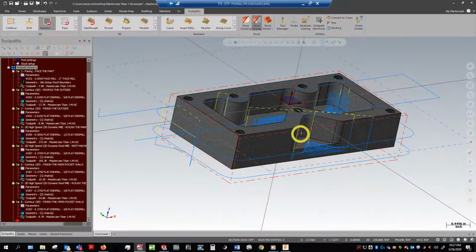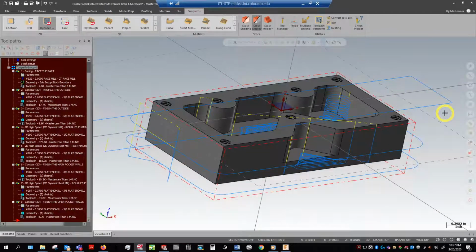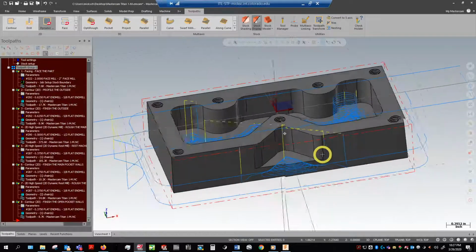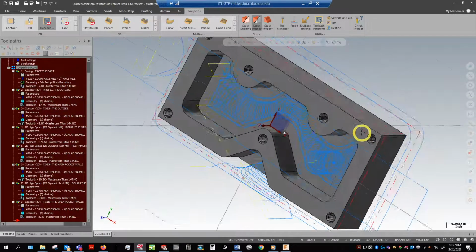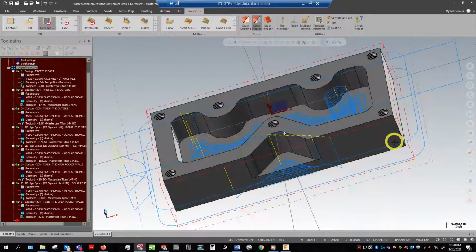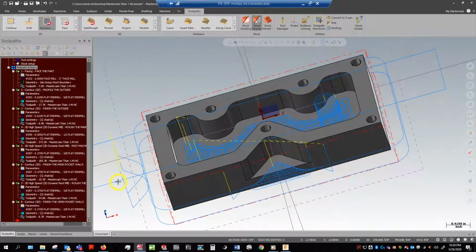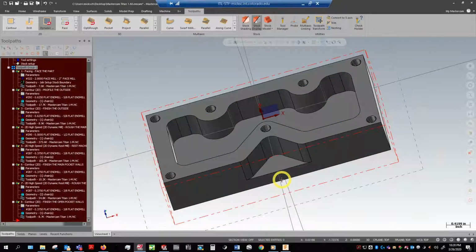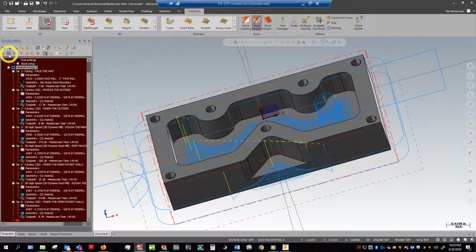Now, one thing that I should have mentioned is this is kind of a little bit of a cluttered looking screen here, right? I've got a lot of toolpaths going on, and let's say I don't like that, right? So there's a quick way to turn on and off all the toolpaths. You can simply press Alt-T. That's going to toggle those on and off. And then you can also, this does the same thing, toggle display on selected operations, same function there.